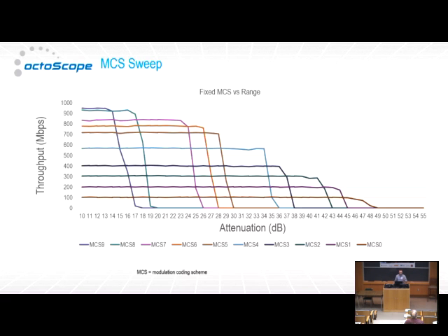And so what we expect a Wi-Fi device to do is to move from maximizing bit rate when path loss is low, right, to maximizing the robustness of communication at very low MCS levels when path loss is high, right. So ideally, we want our Wi-Fi devices to follow right along the very edge of this curve. They want to maximize bit rate for a given attenuation level.